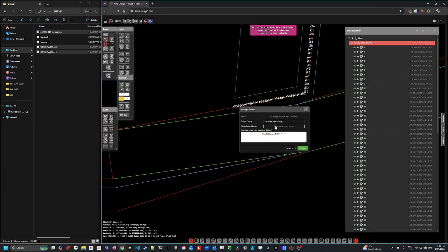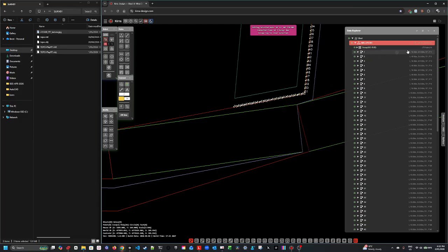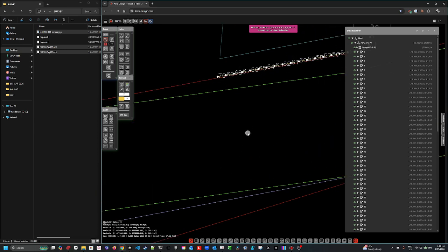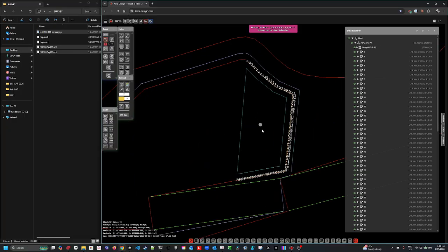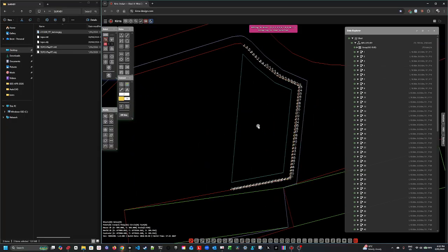And what is this group name going to be called? We're going to call it no sub. Let's just put it as one word, or dash sub, no sub. There you go. All right, assign. Okay, now if it worked, it'll say 70 holes as per a formula. Okay, so now that is a group. So now you can just select on that group instead of selecting one of these holes in here. Okay, I thought that was cool. All right, so the next one is this pattern in the polygon, right? So we're going to use pattern in polygon.